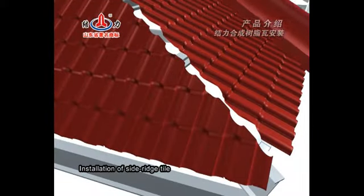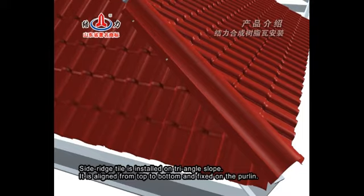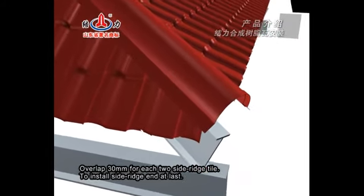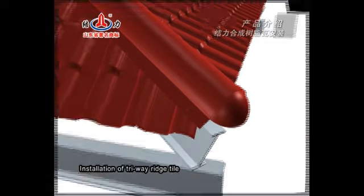Installation of side ridge tile. Side ridge tile is installed on the triangle slope. It is aligned from top to bottom and fixed on the purlin, overlapping 30 mm for each two side ridge tiles. Install the side ridge end at last.